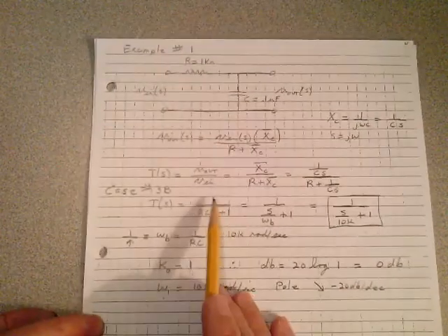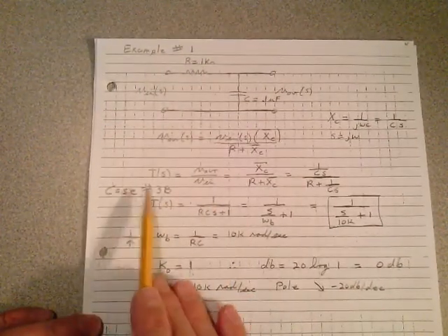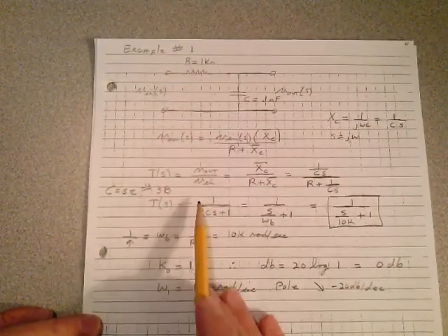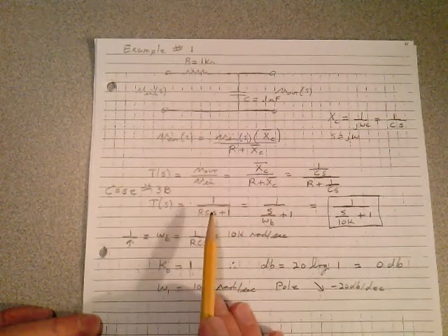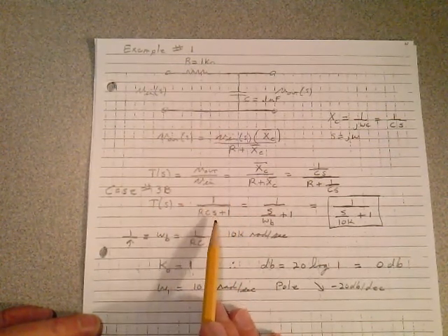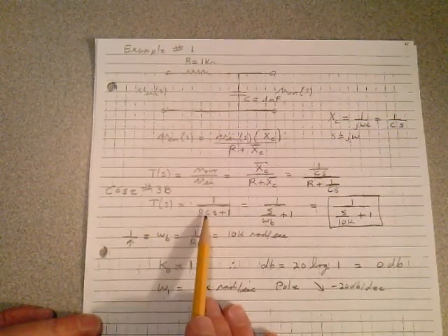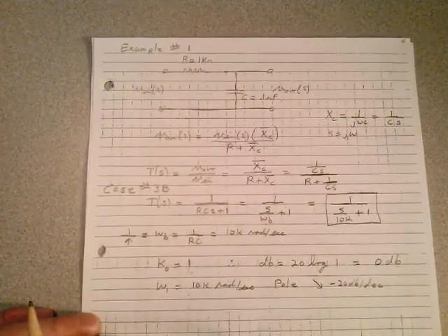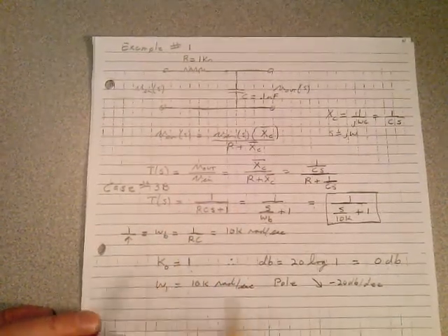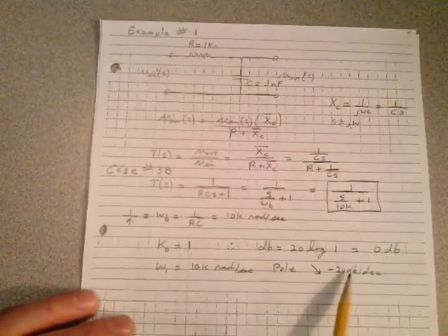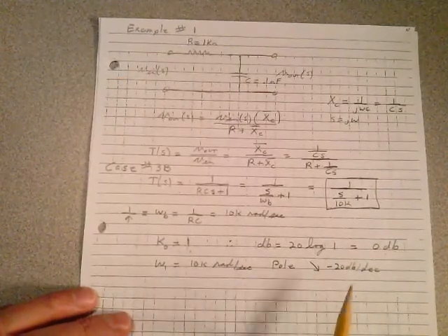Keep in mind, this form we have up here, we called it case number 3B. This form of the transfer function like this is case 3B, and you might want to look back on page 194 on the previous page, and you'll see that that is case 3B, and we already discussed that the pole breaks down at minus 20 dB per decade. So at this point, we're just using that. So what we do is we go to our